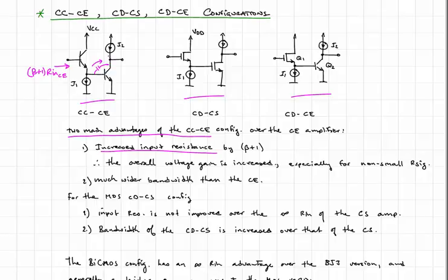So what we need is a better voltage source driving this base. If I had an ideal voltage source here that I could drive at whatever signal that I wanted to, then it wouldn't matter how much current was being demanded of it through this parasitic capacitance, this Miller capacitance. The voltage source would be able to supply it.